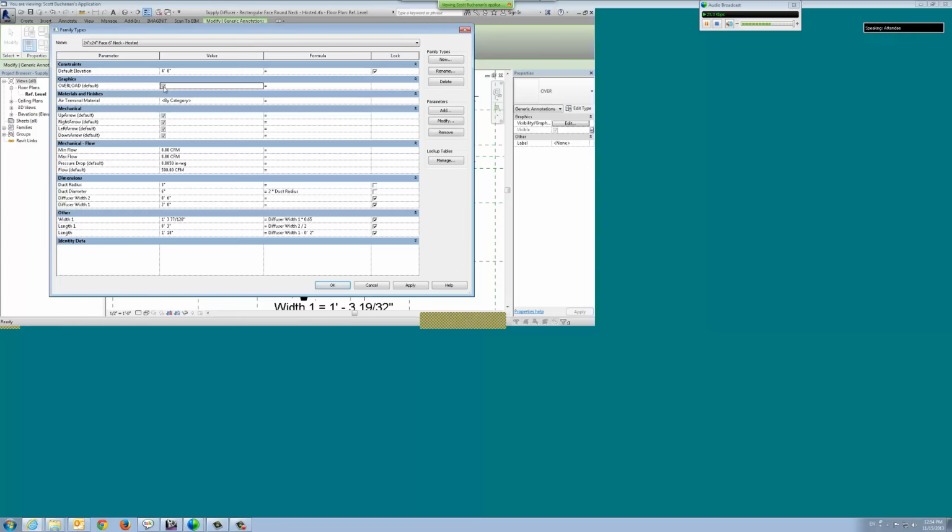Well, I want to take it a step further. I don't want to have to go through that. It kind of defeats the purpose. We want to be notified when someone inputs invalid information. So we have a flow parameter. Okay, that exists. We know it's at 500. We've got the min and max flow parameters in there. So what we can do is put in an actual formula over here to get this yes/no parameter to toggle.